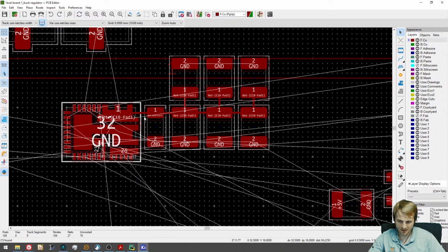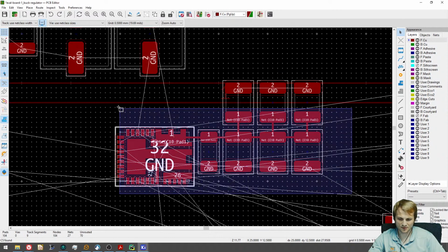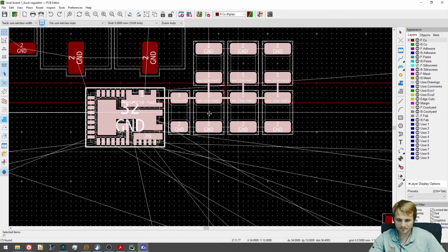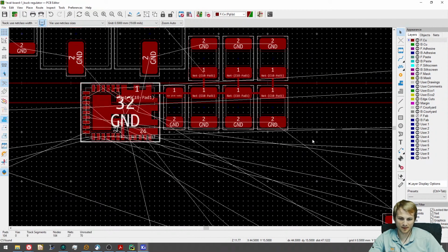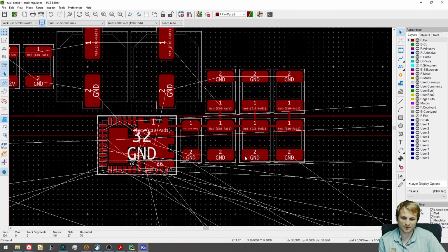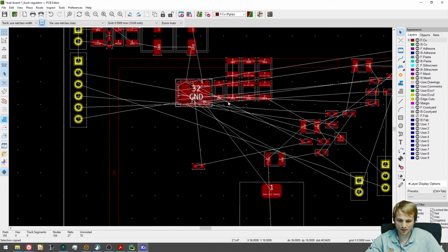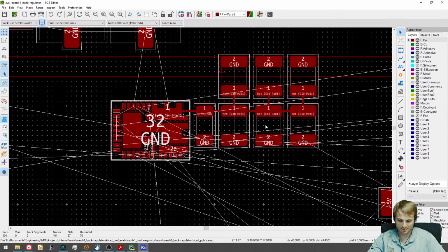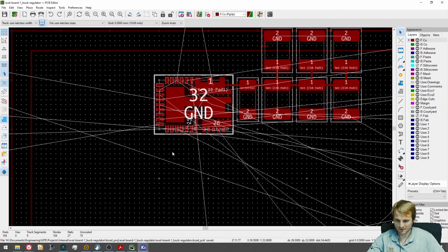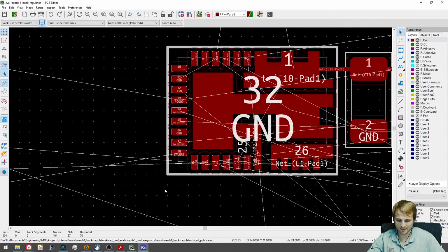So the first thing you want to do with any sort of buck regulator, buck noise is on the input side. So your most important thing on a buck on the layout side is getting the input caps. That's first. Then after that, it's typically working on the inductor. We'll see what our layout recommendation is.